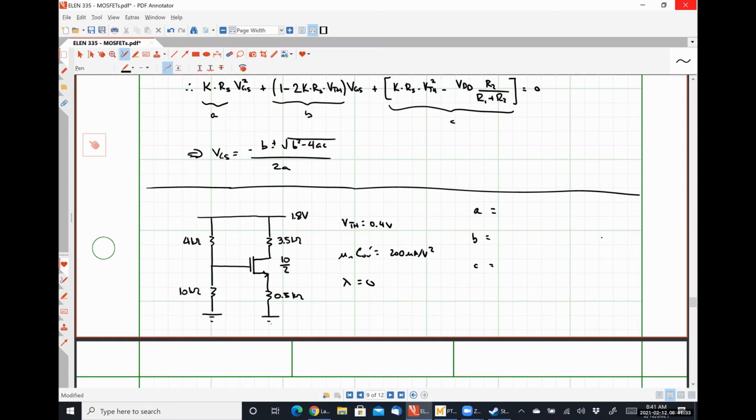I will say that if you use LTSpice to do any simulations to help you out, when you specify an NMOS or a PMOS transistor in LTSpice, it is looking for a physical unit of length for the width and the length of the transistor.